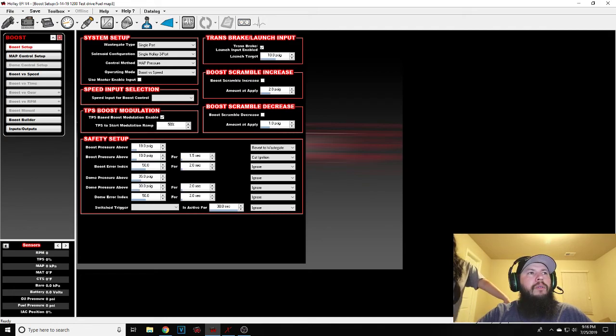We'll see you on the next one, which is probably going to be some track racing this weekend. We're going to help out Randy in the heap, and hopefully get him some personal bests. We're going to switch over to a different power control method. We're going to do his on a timing retard setup in conjunction with some boost control, instead of solely boost control. He just makes a little too much power per PSI to get that really fine control. So we're going to switch to timing control.